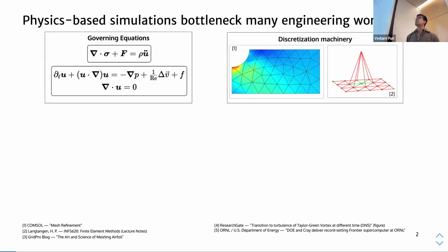So once you have your equations down, what you end up doing is you discretize your domain into a series of triangles and quadrilaterals called a mesh. And inside each mesh element, you solve for your solution using a weighted sum of polynomial interpolants.